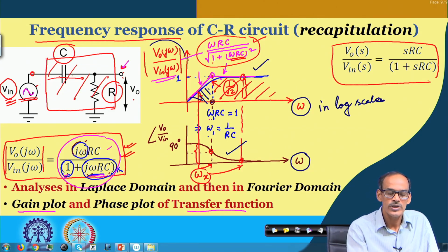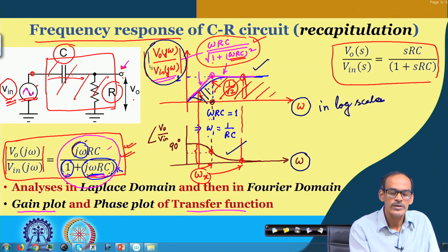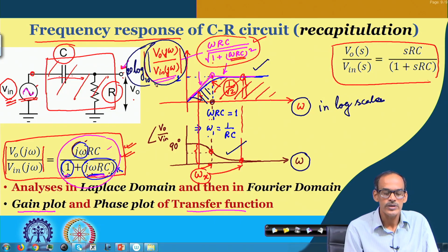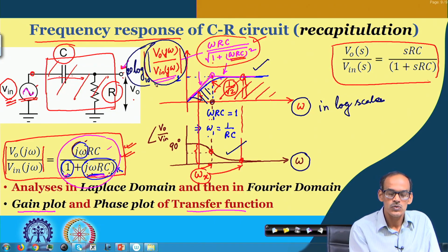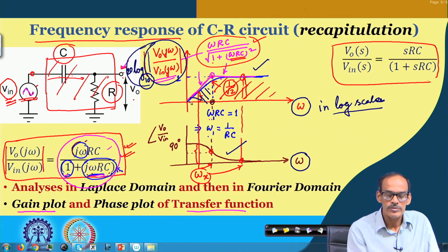and the corresponding magnitude here, instead of considering magnitude, the corresponding data is converted into decibel form. So, instead of taking only the magnitude, it is log transformed with base 10 and multiplied by 20. There is some reason why we multiply with 20, but at least to make you understand why we consider log: it basically captures a wide range of the variation of the gain, particularly in this portion and in this portion.